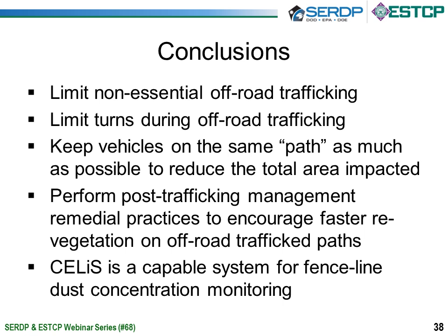Likewise, if it is desired that the traffic surface be smoothed out, especially where large ridges have been created by turning track vehicles, surface leveling operations could be conducted, such as blading or disking. Such remedial practices may make the surface more susceptible to wind erosion, though. So in such scenarios where smoothing out the surface was required, it may be more desirable then to follow up and kickstart the revegetation process with some watering practices, as previously mentioned.